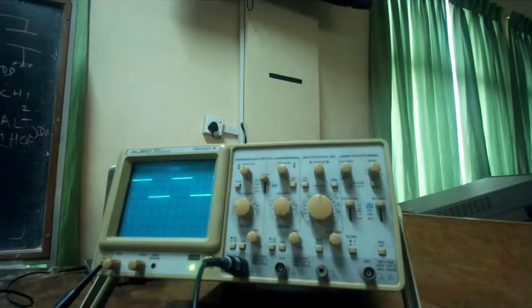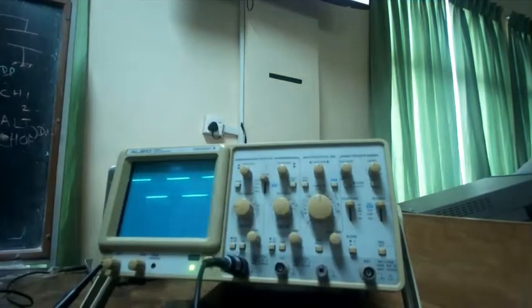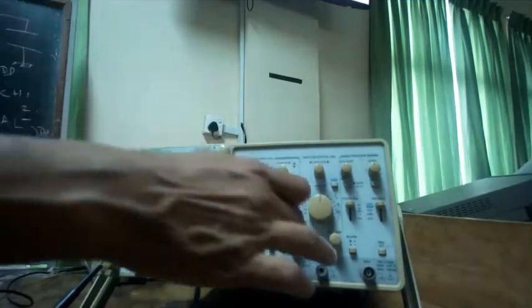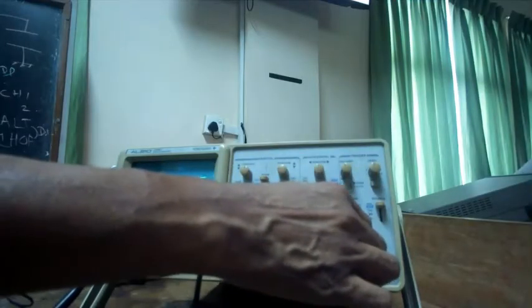Sometimes you have other oscilloscopes where you can uncalibrate it by turning the knob. Some people may hear it around here. You hear a click sound when it goes into the calibrated position, and when it comes out, you don't, so you know that it's not there. So now it's there. In this case, what you have is a pressed button to make sure it's uncalibrated, and then you can change it.